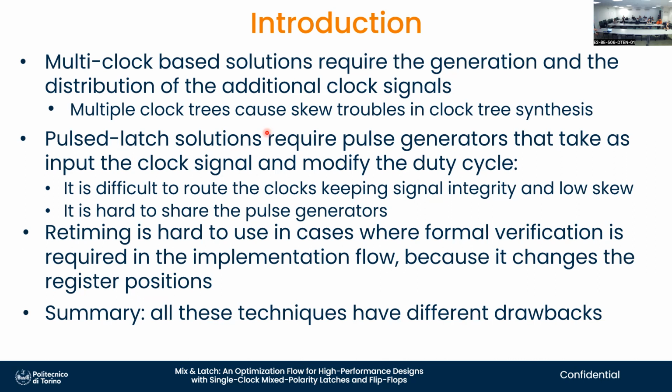Retiming, unfortunately, makes equivalence checking, that the RTL code that you wrote is equivalent to the layout that goes for fabrication, much, much harder. Theoretically solvable, but very, very hard. And as far as I know, to the best of my knowledge, not done in practice. Okay? Because moving registers is difficult.